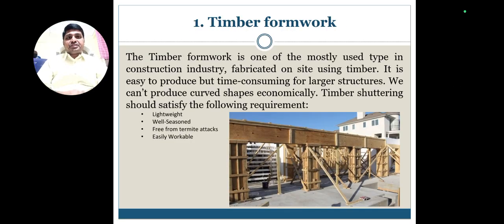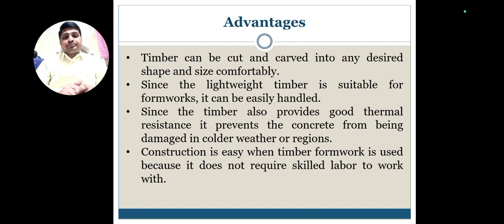While coming to the timber formwork, it is one type of formwork which is basically manufactured with timber material. The members used are lightweight, well seasoned timber, free from termite attacks and easily workable, so the timber formwork has a number of advantages when used in the construction site.